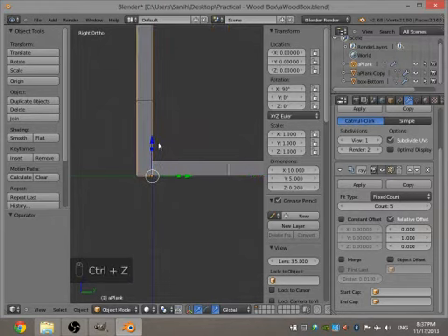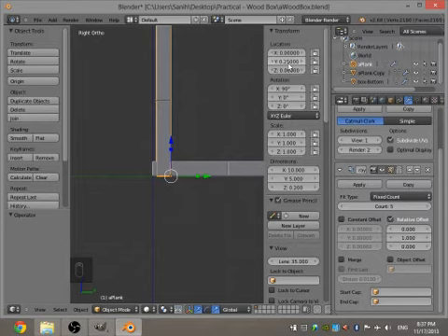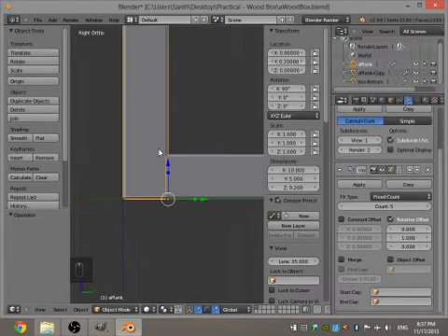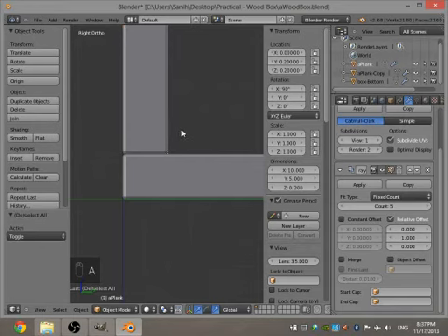Oh, right. What was the thickness of this thing? 0.25, right? Yeah. Whatever the thickness is, move that much. So the y-axis, 0.25. Was it 0.25 or 0.2 we gave? I think I gave 0.2, not 0.25. Yeah, but it's okay. 0.2 I gave. Now I need to move it up by this thickness, and that's also 0.2. Y-axis, I need to move it up 0.2. Now that's perfectly placed. There's no error there.